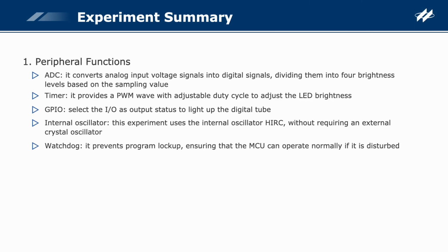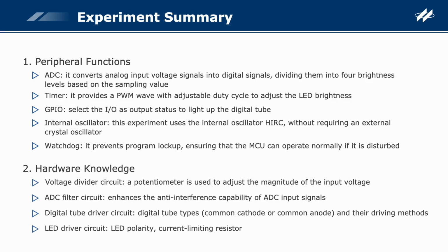Experiment summary. This comprehensive experiment uses multiple peripheral functions of the HT8 MCU, including ADC, timer, GPIO, internal oscillator, and watchdog. The hardware circuit includes a voltage divider circuit, an ADC filter circuit, a digital tube driver circuit, and an LED driver circuit.